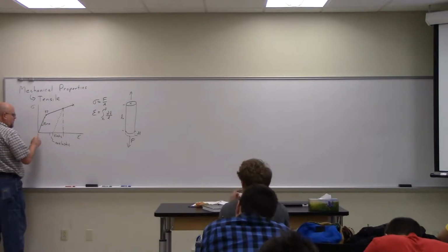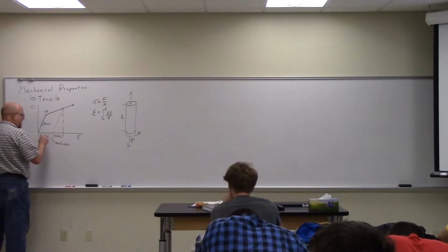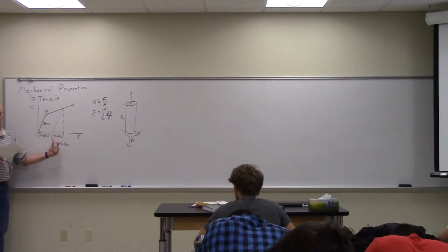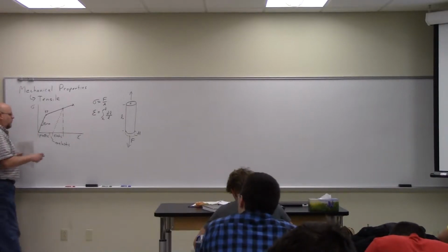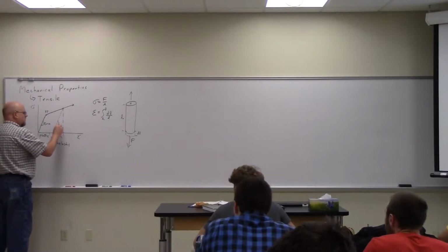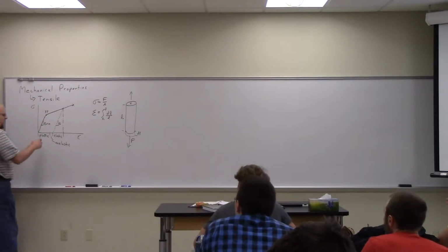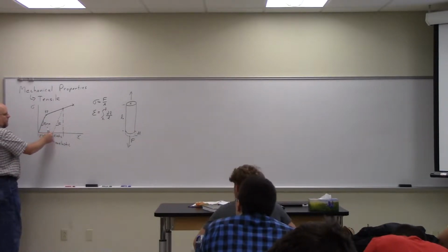And then the part that you're permanently stuck with is plastic deformation. So we have plastic, anelastic, and elastic. And the slope here is again the same modulus as the elastic portion. Is the plastic supposed to be from under the yield point over? Nope, the plastic is just some portion. It's just these three pieces. Anelastic, typically in most materials, is very small.